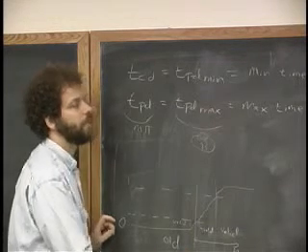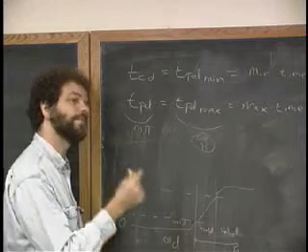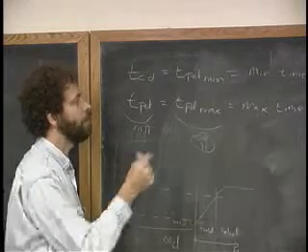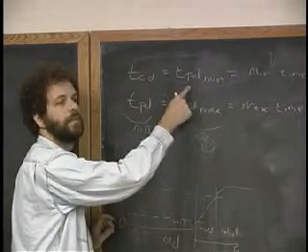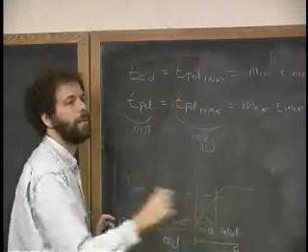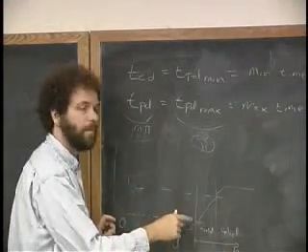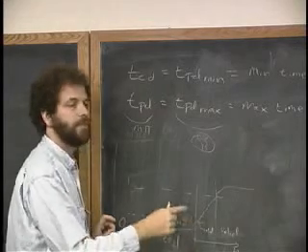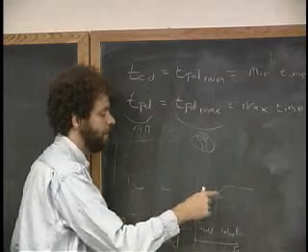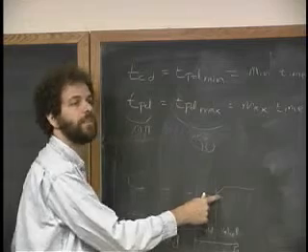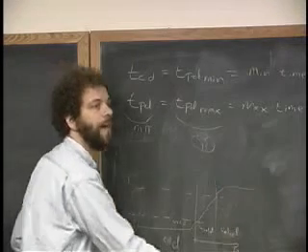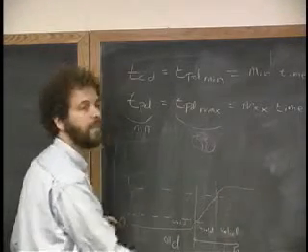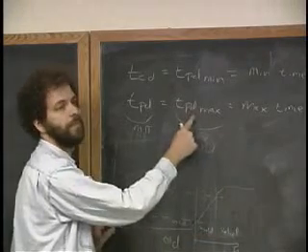Well, the answer is that it guarantees it will continue to produce the old result for at least TPD min, the minimum amount of time for invalid stuff to propagate through the circuit. And then the question is, once I finally send it the valid new stuff, how long does it take for the valid new output to happen? And the longest that could take is TPD max.